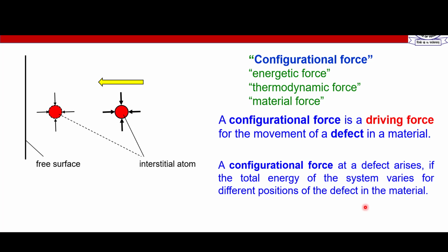And now let us look a little bit at the concept of configurational forces. Why are we looking at this idea of configurational forces? Because we have discussed some problems with the concept of J integral. So we know that if there is a real material which deforms plastically, then J integral is not valid. You cannot allow unloading or non-proportional loading, and that is inevitable. If the crack grows, then there is unloading.